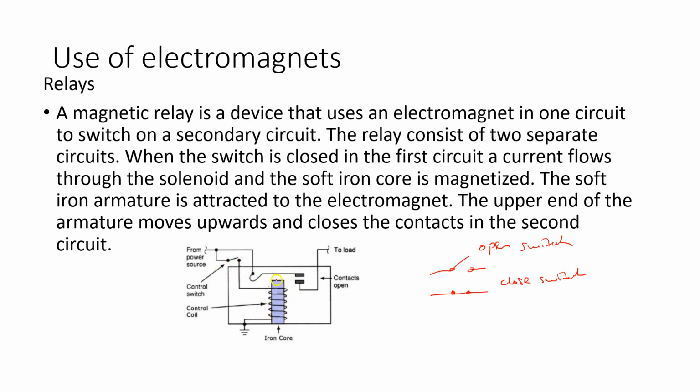And when this solenoid becomes magnetized, it allows this contact to move down to the magnet so that it can touch it right here, right? So imagine that this is now your new contact. It's touching against this other contact, which just means that current can now flow to the other part of the engine to tell it to turn on and start. You understand?